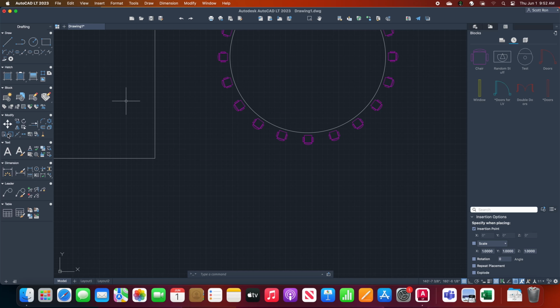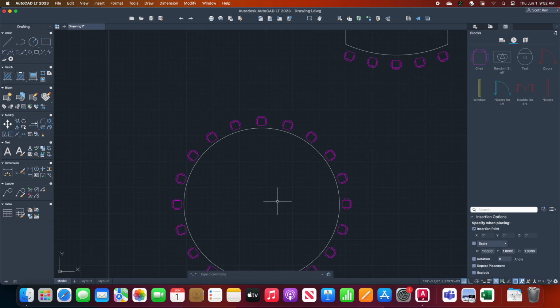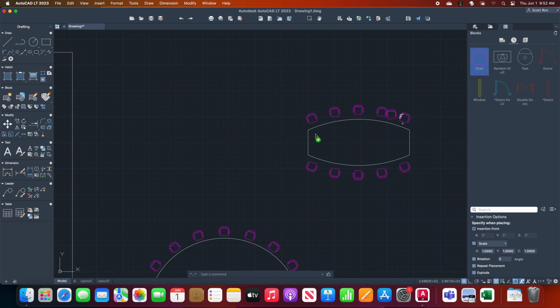Okay. I just showed you mirroring. Does anybody have questions on mirroring? If you want to just reflect, like once again, just a chair over here. Now I want this chair to be on the opposite side, so I select mirror, select your first object, press enter. Now what's the mid? Any point you select, it's going to act as the middle line. So I'm just going to look for the appropriate middle line. Ta-da! There you go. It's mirrored. Okay, easy.